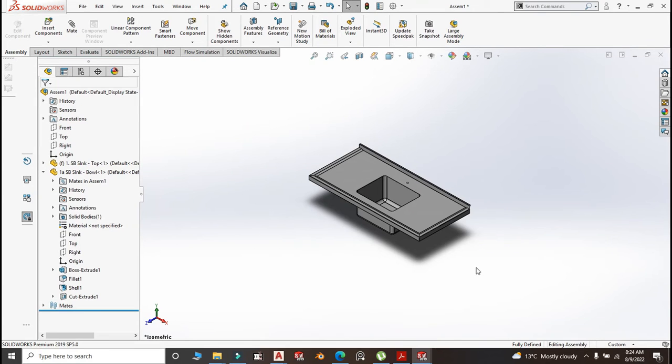Very many people normally encounter all sorts of troubles when they are welding the bowl to the top. If you are not very careful with it, you will start doing some notching, and at the end of the day your bowl won't be neat, it won't be straight. You will have some issues with it.